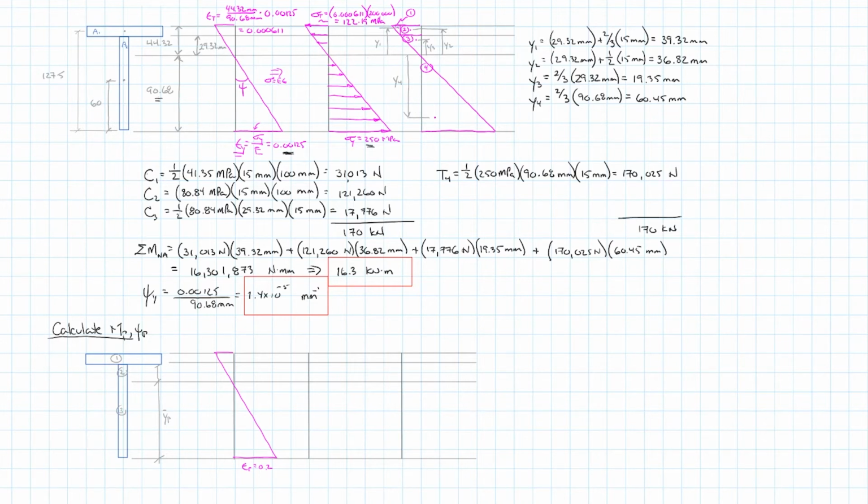Now, one of the things to be aware of is I've erased the dimensions that we had because the neutral axis, although I didn't bother to show it having shifted, will actually occur at a different location than it did during the elastic capacity, and that's because the cross-section itself is asymmetric.